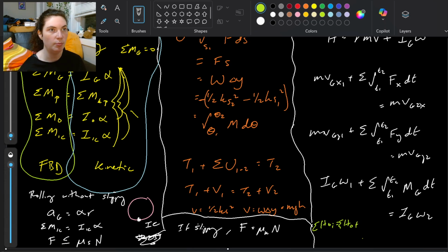And for impact problems, we had the coefficient of restitution also included in that. So that's our v_B2 minus v_A2 over v_A1 minus v_B1. Those are when we had impact problems where things were bouncing off of each other. Otherwise, if we had other types of collision problems, we were probably just using our conservation of momentum without a coefficient of restitution included.